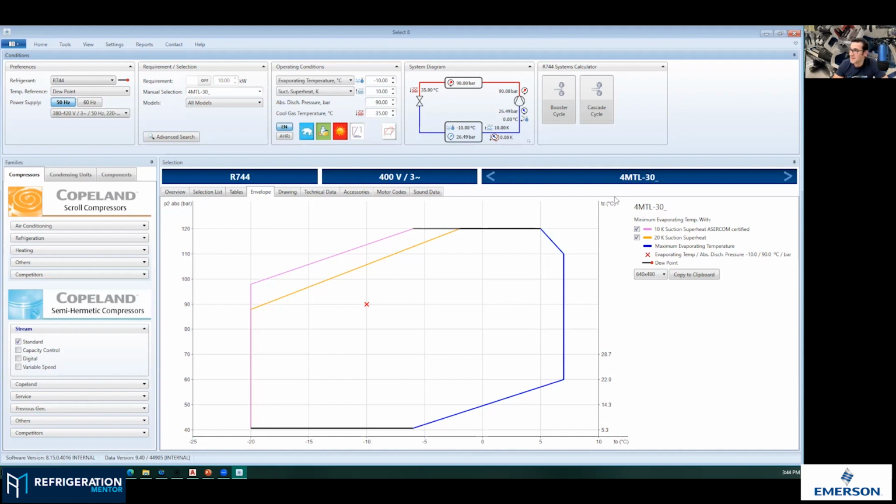So I love that you brought that up. Yeah. And in this high load region or high evaporating temperatures region, you have very efficient motor cooling. So in some combinations of the operating condition, it can happen that you will not see the motor temperature trips. So as you just said, you will only continuously overload the motor by the extremely high currents without even motor tripping on temperature, because here you have really good cooling of the compressor, but still it cannot run at too high amps. And that's something good to know.